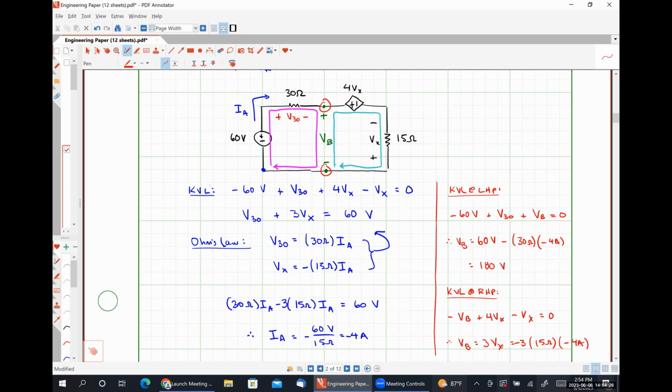To that I say, think about it like you were taking the voltage drop between 2 points in a circuit with a multimeter. It doesn't necessarily have to be over a single resistor. It can be over some combination of circuit elements. And that's exactly what we're doing here. As long as we can identify 2 different points in the circuit, and because voltage is simply the potential difference between 2 points in a circuit, we should be able to use KVL to determine what that voltage drop is.